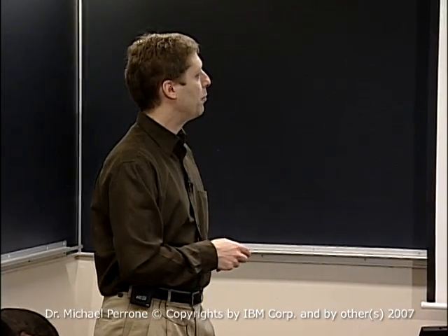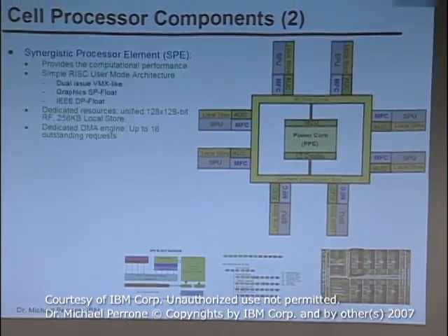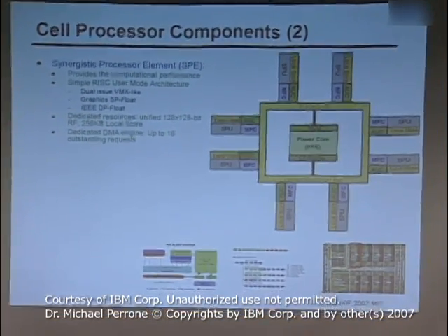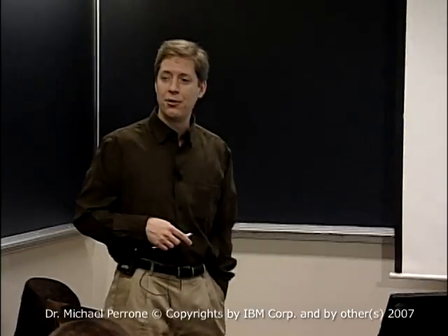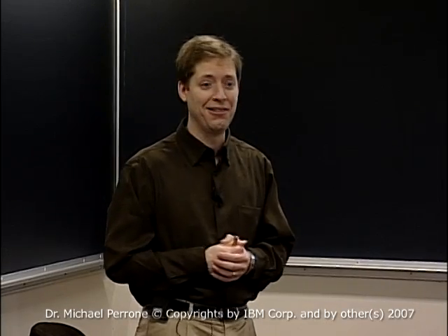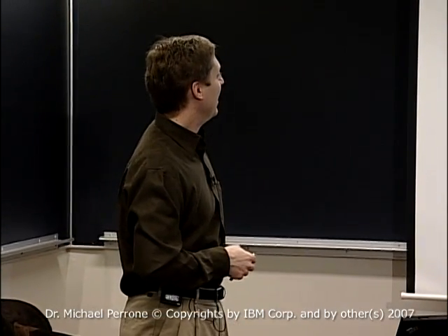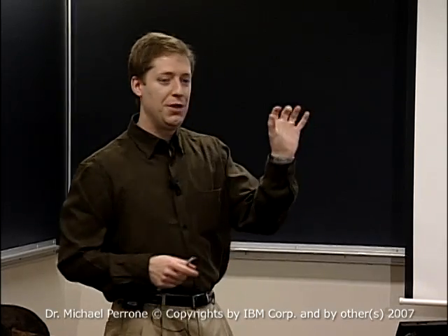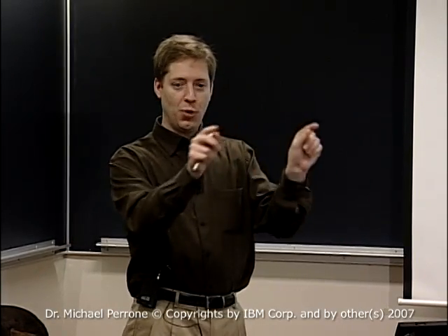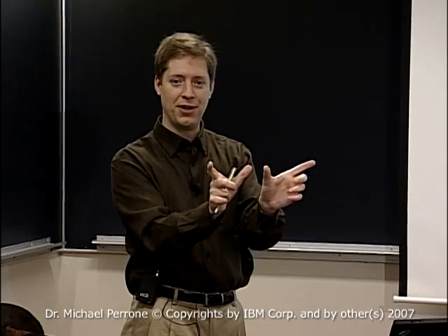It has IEEE double precision floating point, but it doesn't have IEEE single precision floating point. It's a curiosity, but that came from the history. The processor was designed for the gaming industry, and the gamers didn't care. They didn't want IEEE. Who cares about IEEE? What I want is to have good monsters on the screen. And so those SIMD registers can operate bitwise, on bytes, on shorts, on 4 words at a time, or 2 doubles at a time.